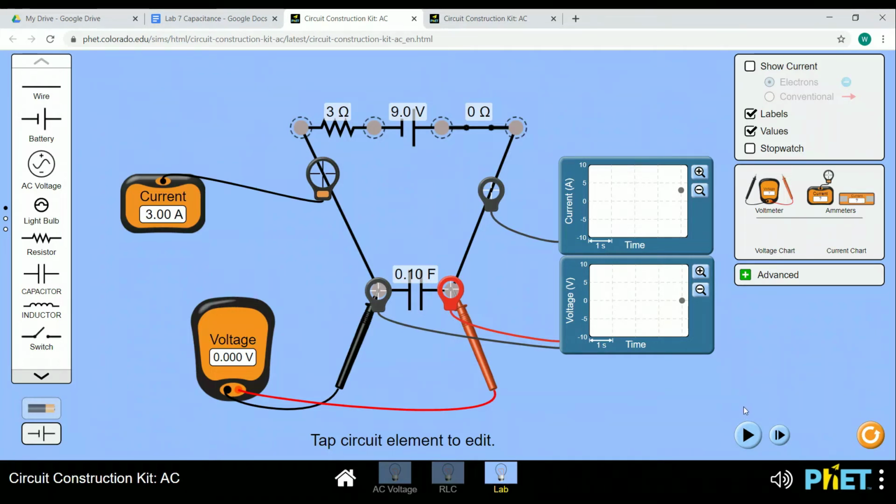So what happens now when I start time? Well, wait a second. Let's go one step further. Let's introduce a stopwatch. And I've got it set to go. It'll go when time goes. I'm going to watch the voltage change, and when it hits a peak of 9 volts, I'm going to stop it. Bad attempt because I'm using my reflexes to do it, but it'll do. And off it goes. You see it goes up, and it's 9. And that says 2.68 seconds. Probably it's a little less than that.